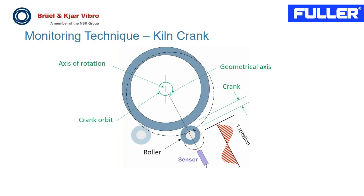And it is important to know that reality is not as ideal as we see in this photo. The roller here may not be completely cylindrical. It can have imperfections, pitting, and out of roundness. This we of course overcome by introducing some filtering techniques. So the only contribution that we get is the cyclic variation corresponding to the kiln speed frequency. And this is basically the deflection of the supporting roller due to the kiln crank.